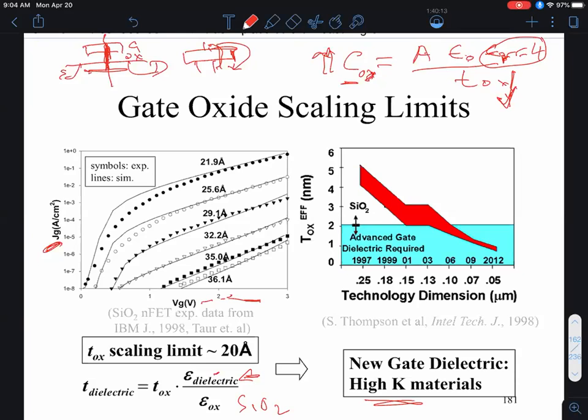Okay, these are generally known as high K gate dielectrics, where instead of a relative dielectric constant of 4, you have much higher dielectric constants. The current champion is something called hafnium dioxide, which has a relative dielectric constant of approximately 25. Let's say 24, so 6 times as much as oxide. So for the same physical thickness of the dielectric, when you go from silicon dioxide to hafnium oxide, your oxide capacitance would go up by a factor of 6.